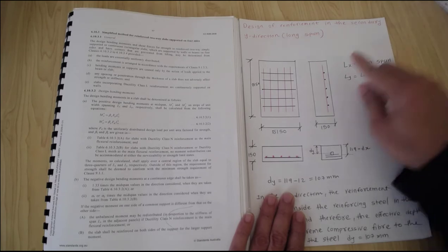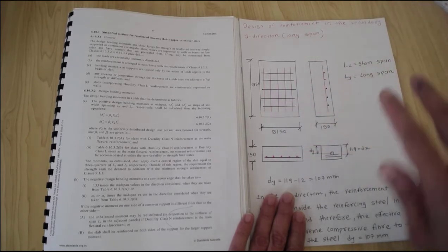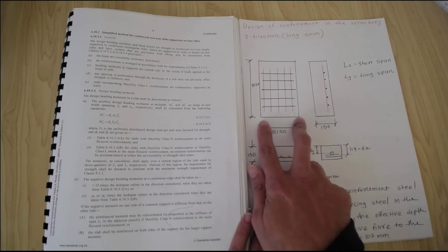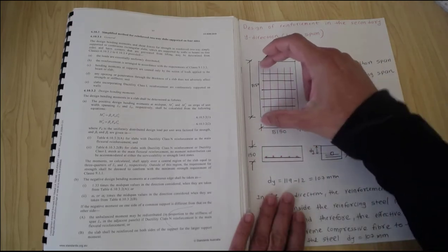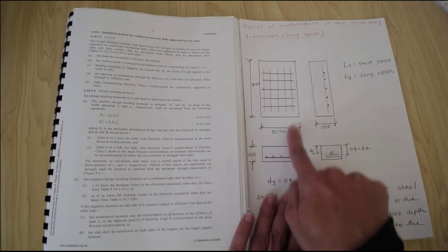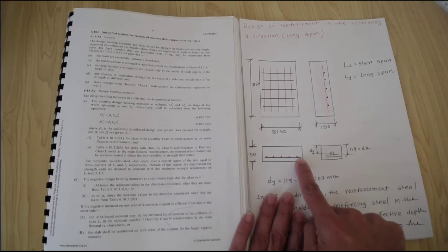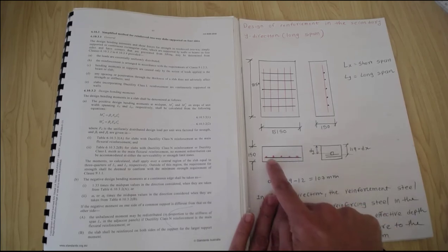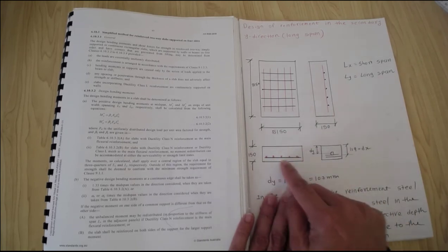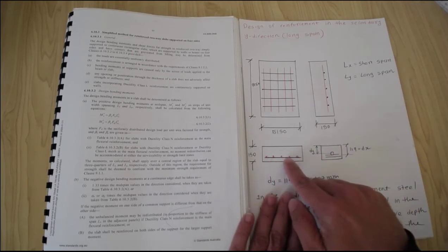Now the x is the shorter span, so it's not your horizontal and y axis; x is generally classified as a short span and y is classified as a longer span. I also drew these cross sections. When I'm looking from this side, I can see this bar, the red one, that is the secondary reinforcement, and these are the primary reinforcement, the blue one. Primary reinforcement is generally provided at the bottom surface.